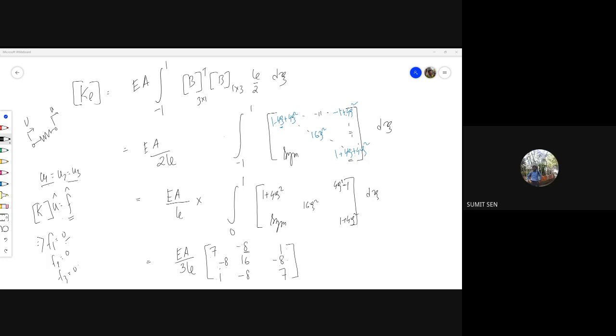Yes, sir. So the system is in equilibrium. The net force should be 0 if all the deflections are the same, which is only possible if the coefficients add up to 0. Okay, so we got the stiffness matrix.